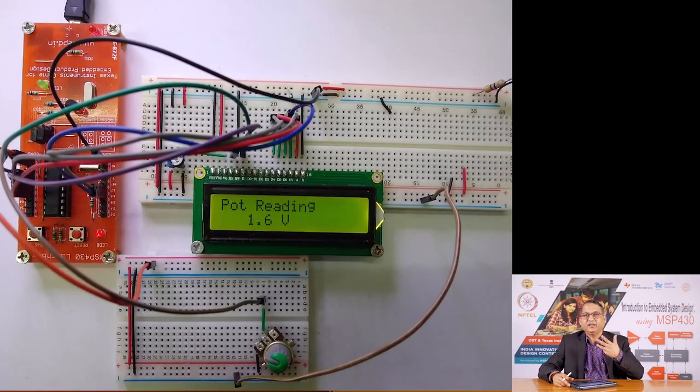Here is the code. I am not going to go through that code. This is nothing but a mix of code for the previous exercise of reading the ADC value connected to the potentiometer and changing the duty cycle. Instead of changing the duty cycle now, we are outputting a number onto the LCD. Here is the display that you see. It has been converted into a voltage, instead of a binary number. So you should see the voltage going from 0 to 3.3 volts, because we have chosen the reference to be 3.3 volts, which is the power supply voltage.